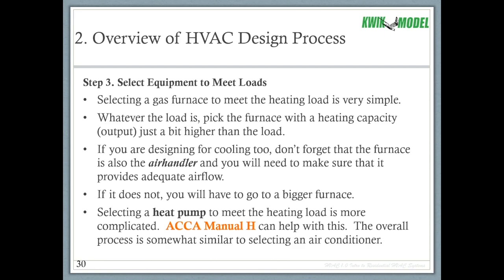On the heating side, oversizing equipment doesn't cause quite as many problems as oversizing cooling equipment, but it still potentially can cause issues, so do be careful with that. Don't go too big on your equipment, but you do have to get airflow. You may have to change the brand of equipment or the line of equipment in order to get more airflow without so much heating capacity.